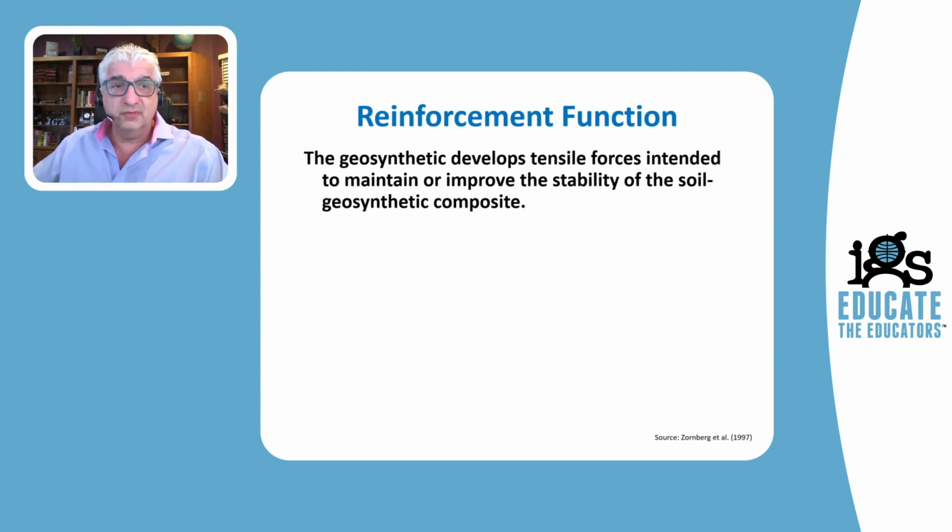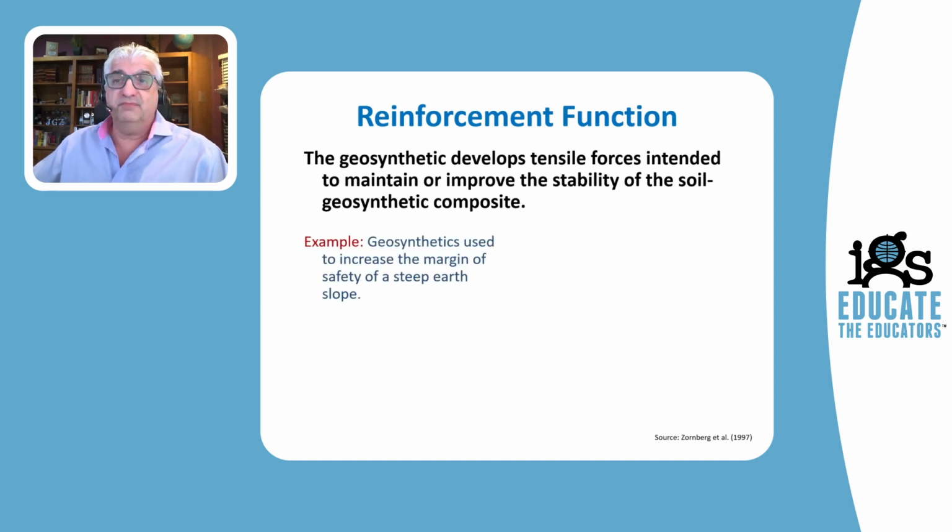Let's go to the second function, which is reinforcement. In this case, we are going to ask more from the geosynthetic. We're going to ask not only to survive installation, but also to develop tensile forces. These tensile forces are intended to maintain and improve the stability of a geotechnical system. That is, we want to avoid collapse. An example is when geosynthetics are being asked to develop tensile forces to increase the margin of safety in a reinforced steep slope.